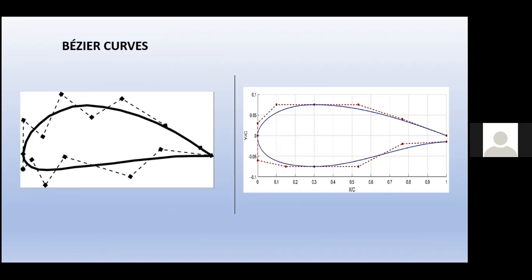As a parameterization method, the Bézier curves method was used, in which 13 control points were used to control the shape of the airfoil geometry and which allowed moving a single point to obtain a different geometry by means of an algorithm based on gradients that uses Xfoil itself within its code to evaluate the performance of the geometry. Everything was an iterative process with which the modified airfoils that will be part of the wind turbine blades were obtained.